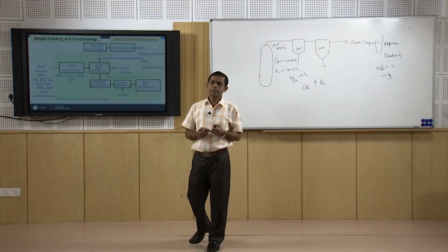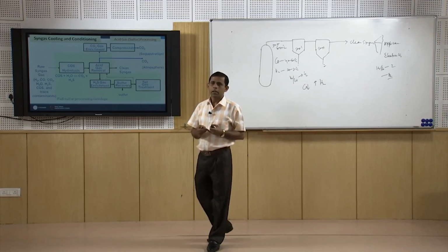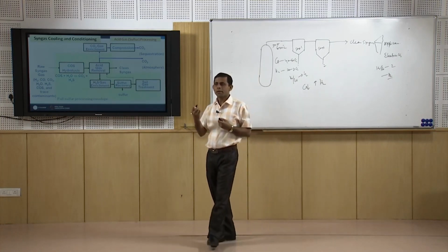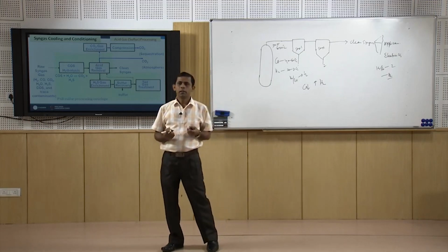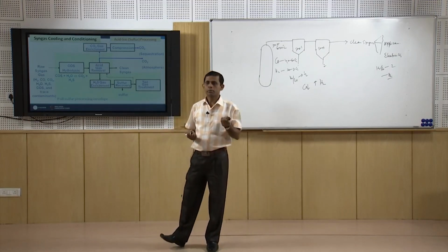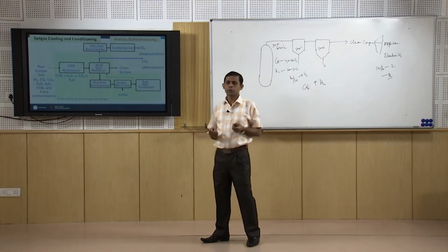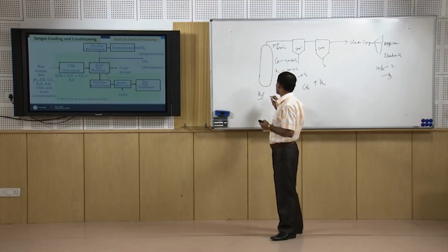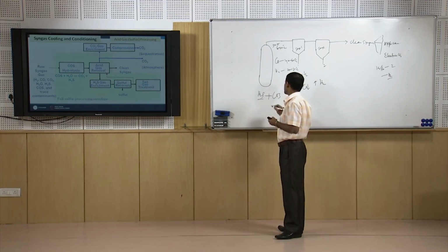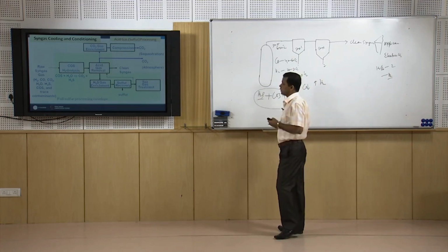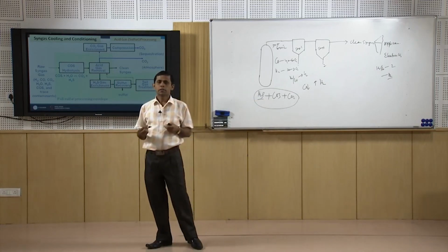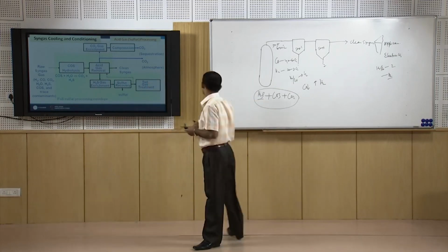Obviously, the acid gases COS, H2S etc. There is no NOx in this case, it will be nitrogen, because we have supplied a controlled amount of oxygen. There will be no SOx also because we have supplied a controlled amount of oxygen. So, if sulfur is present in the feedstock, it will be available as H2S. So, our major concerns are H2S, COS and CO2. These three are major concerns, we have to remove them, but if chlorine is present in the feedstock, then another addition will be HCl or chloride.